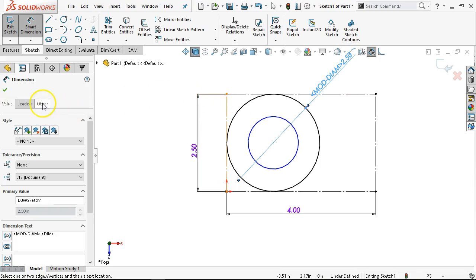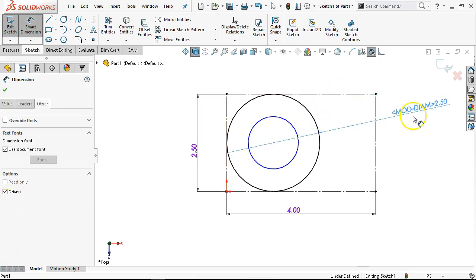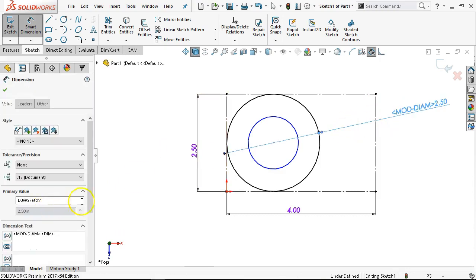Oh, well, I'm also in the condition that those three tangencies are now overwriting, and I've selected in my settings to not show me the warning for the over-defining condition, just go ahead and take that dimension and make it driven.